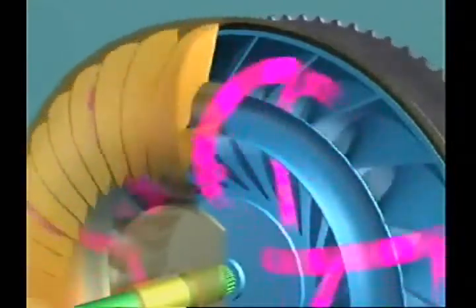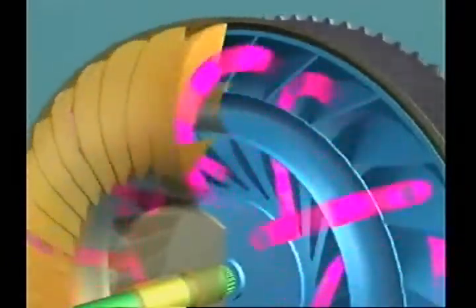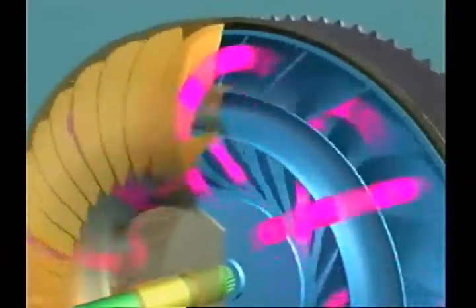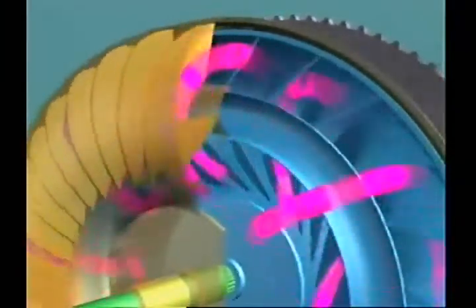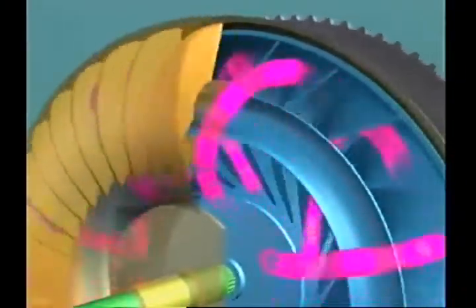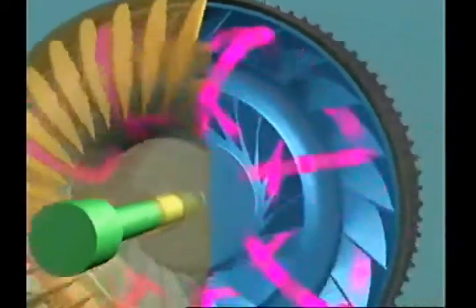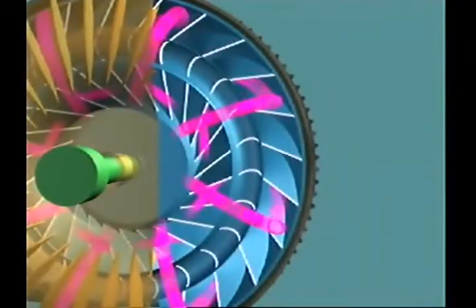This exerts a turning effort against the back of the turbine vanes, which absorbs energy in the fluid, causing the turbine to rotate and transfer the drive to the transmission. The fluid, still at high velocity, now flows between the turbine vanes, leaving the turbine in a direction opposite to impeller rotation. This is due to the curvature of the turbine vanes.